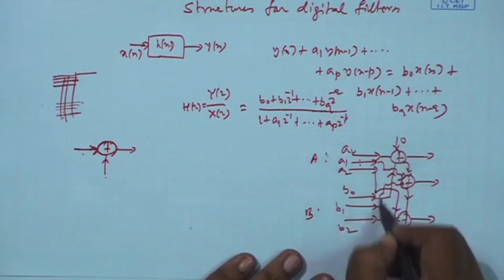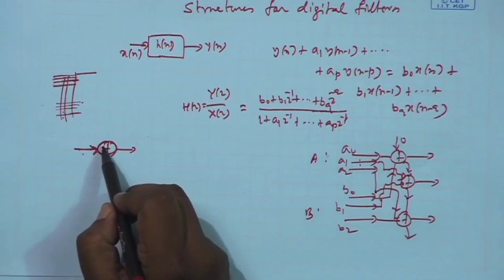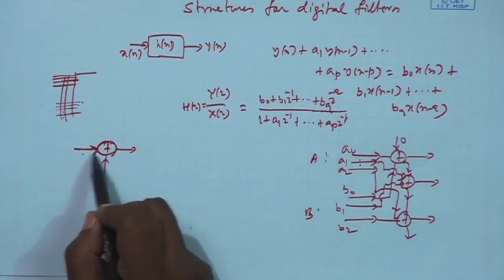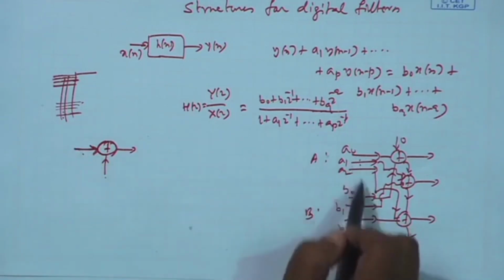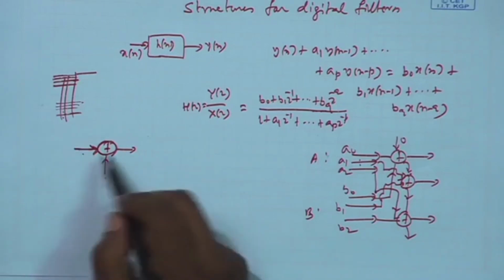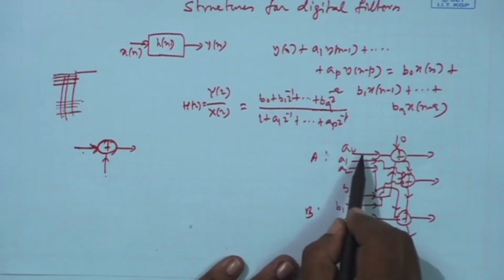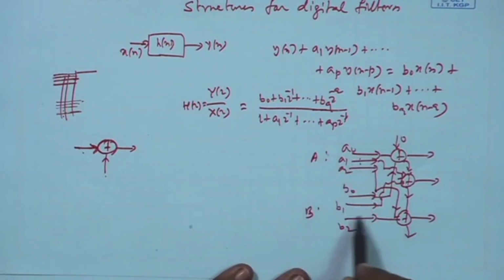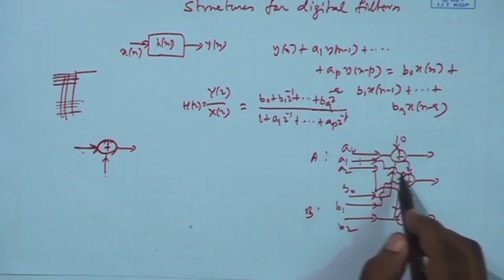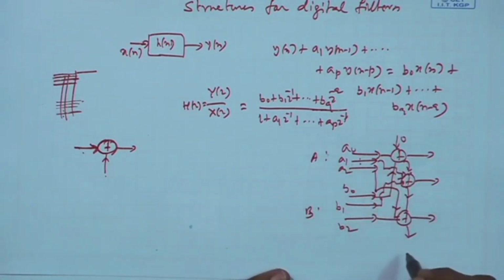So, this total array is indicated by this adder, and this is one line, one bus of however many bits. This is only a schematic. It means a structure like this, where there will be parallel lines for the bits of one data, another parallel set of lines for the bits of another data, and there is bitwise addition starting from LSB and carry propagation. Okay. This is the meaning of this.